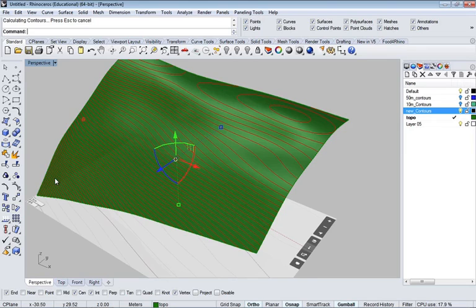The best is to do just every contour and have it solid. That really makes the best quality model, but that's expensive, so think about how you work smartly. Another thing you can do, if you get into it a little more, is start to cut sections.